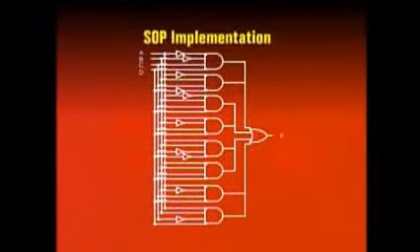The sum of product based implementation of the adjacent 1's detector circuit is shown, implemented directly from the function table. The implementation uses the maximum number of gates. The total gate count is a single 8 input OR gate, 8 4 input AND gates and 10 NOT gates. Altogether 19 gates are required to complete the circuit. The increased number of gates increases the cost, the size of the circuit, the power requirement and the propagation delay, which is of the order of 3 gates.